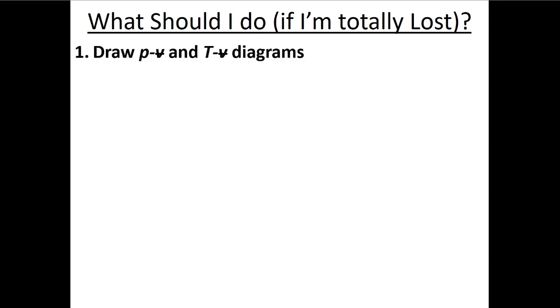So the first thing that I think is useful is it's nice to be able to draw things like PV and TV diagrams. I think there's 2 reasons why this is good. So if you can draw a PV diagram, then you remember as you go between different states that the work is the integral of P dV, and that's going to be the area under the curve for your process on a PV diagram.